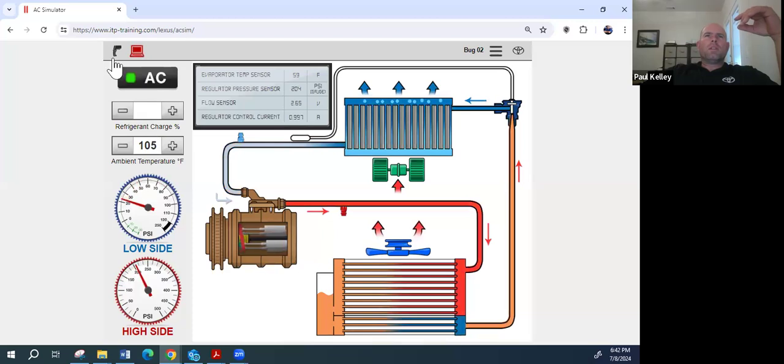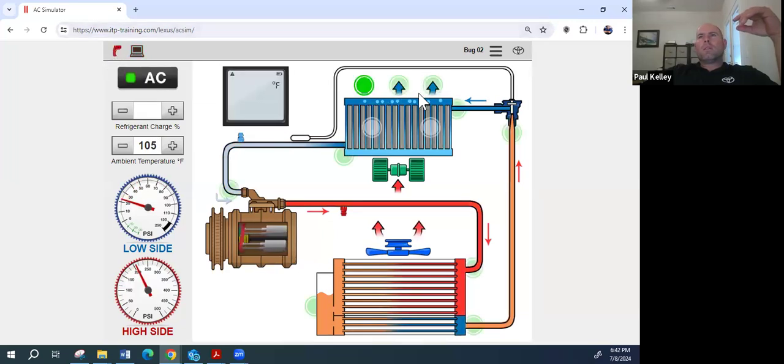I'm gonna turn on the AC, get the temperature like we did, and I'm gonna measure. 76, that's not good. It's not horrible, not good. 83, 87. You guys notice something? It's starting cooler and getting warmer from the right side to the left side.